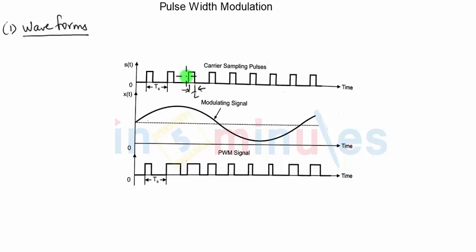So any pulse modulation is nothing but similar to sampling, and hence we are using the notation sampling time period and sampling frequencies. But yes, it is PAM which can be defined to be sampling, especially when we talk about natural practical sampling. In PWM and PPM, we use pulses as carrier signal, but because we are not changing the amplitudes, we are changing the width in PWM, it is not exactly the same as the sampling process.